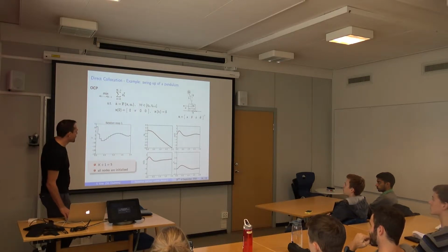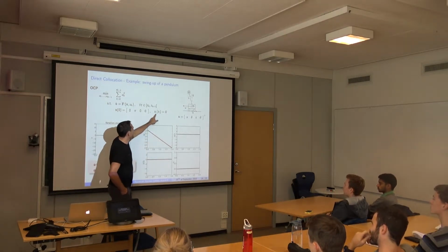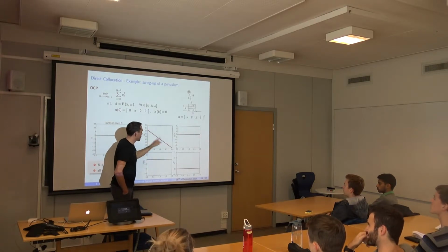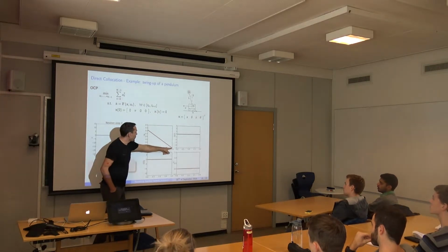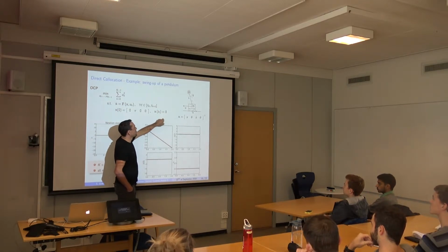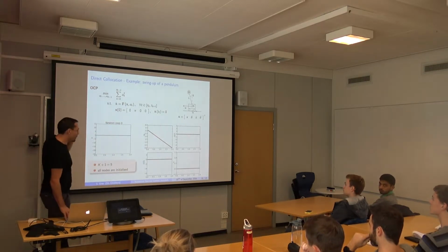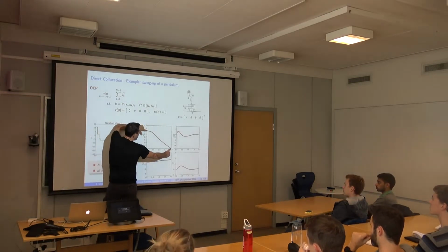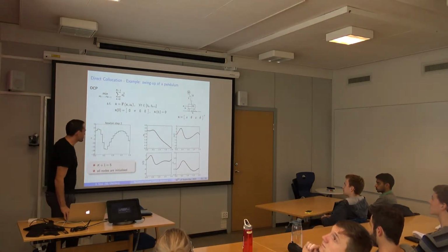So if you start iterating, first, okay, maybe the problem starts feasible in terms of the terminal constraint. So I pretend I hit the target even though the trajectory itself is not physically meaningful. And that will remain feasible throughout because this kind of constraint here is linear, and that's the last theta in the list being 0 essentially. And also it will stay there, Newton will not change that. So you see the trajectory essentially clamped between the boundary conditions and the shape being modified by the NLP solver.